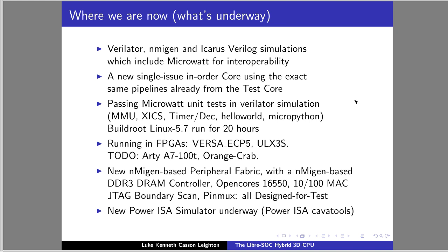Just in case one thing doesn't work, we're actually going to integrate the PinMux into the JTAG boundary scan, so that over the JTAG interface you can tell the PinMux that you want to connect the I2C device to pin X5, and then next you want X5 to connect to the UART transmit line. Right. So that's what it's doing. It's quite innovative.